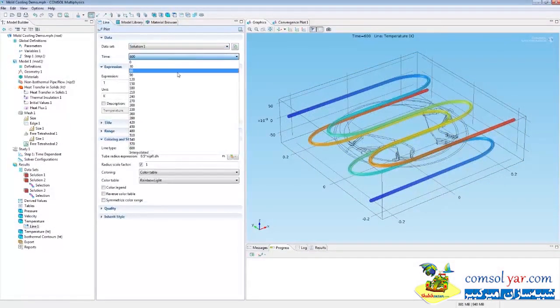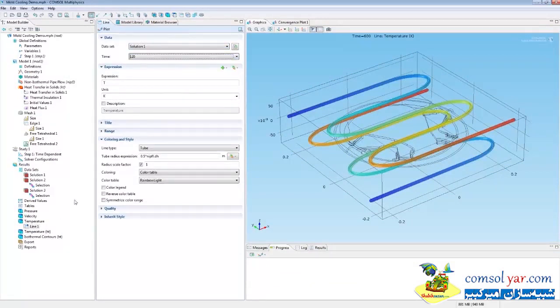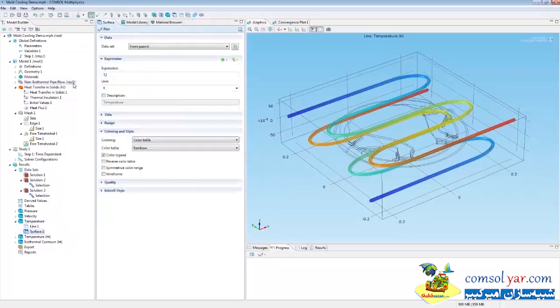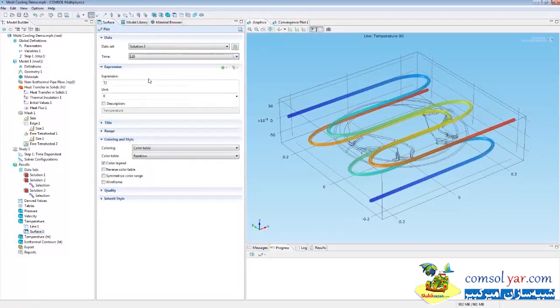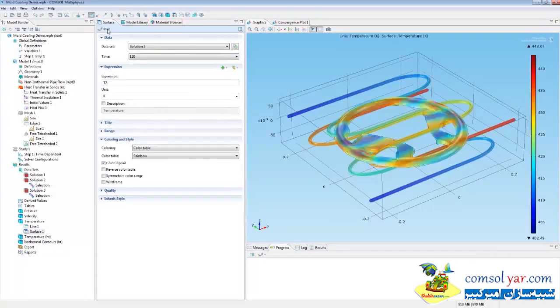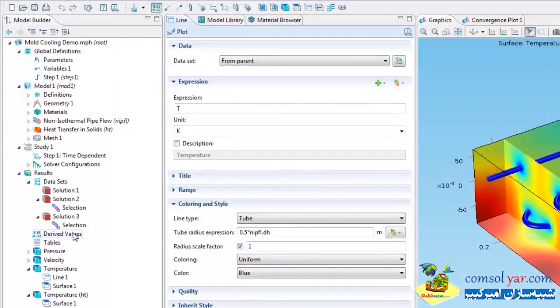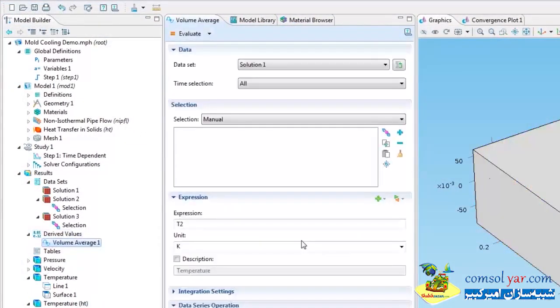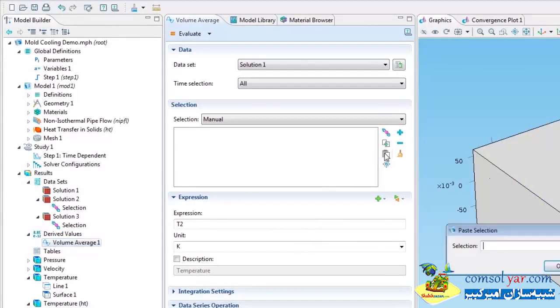With the model solved, I can now use a number of the different post-processing tools in COMSOL Multiphysics to present the results in an informative way. The visualization tools are augmented by other post-processing functionality, such as easily calculating the average temperature in the steering wheel over time.